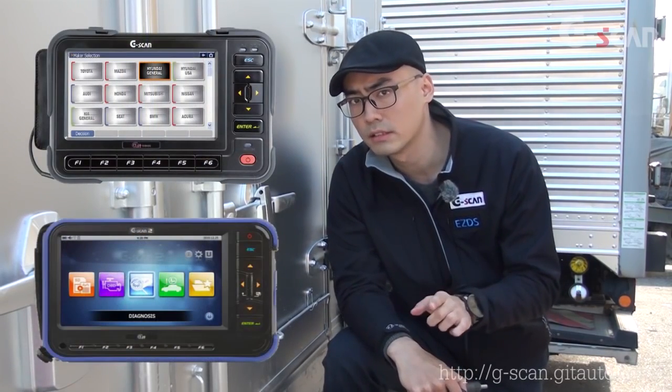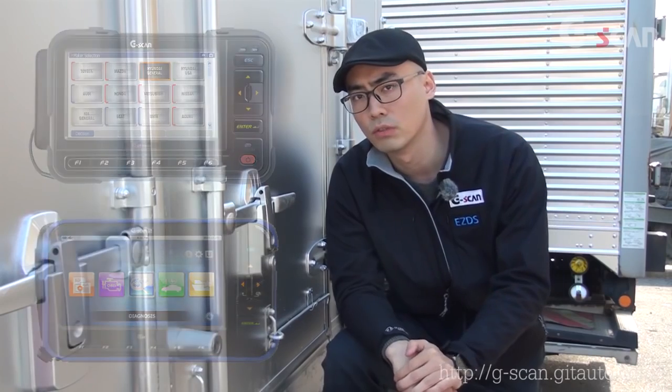From mid-2000s, almost all vehicles are equipped with a bunch of electronics, such as computer modules, solenoids, and sensors. For the purpose of achieving advanced comfort or outstanding performance, engine computer units started to save or learn data from the operator's driving habits. Inevitably, the importance of computer control has been increasing. Whenever you perform repairs on most recent systems, even simple replacement of sensors, you must use a scan tool to reset or erase learned data in ECU.